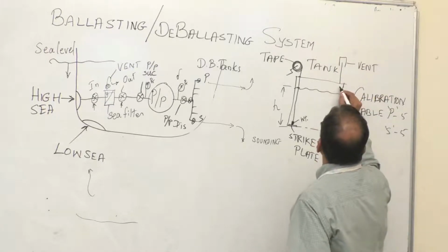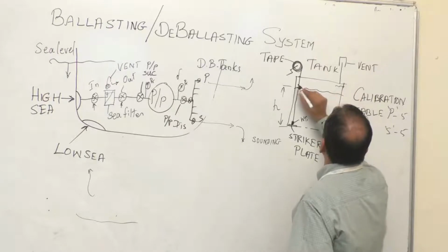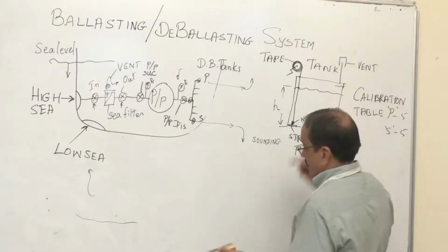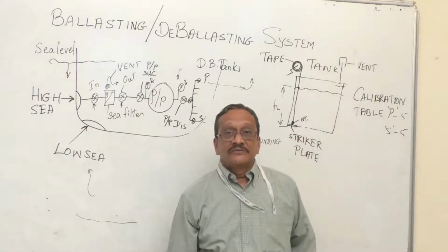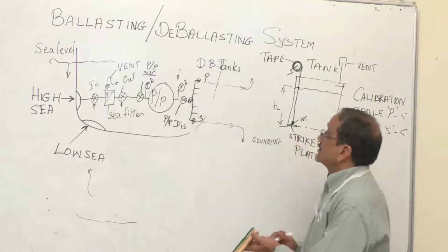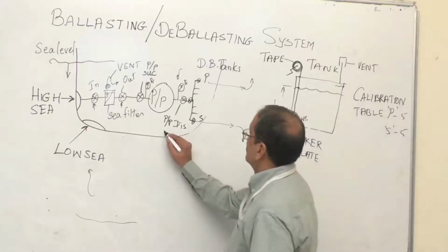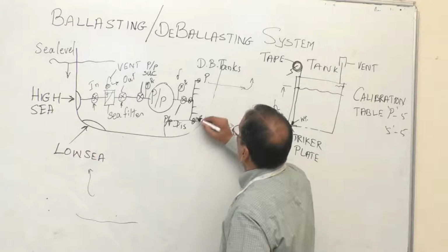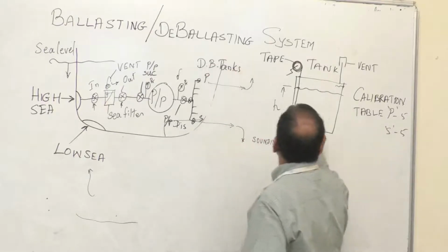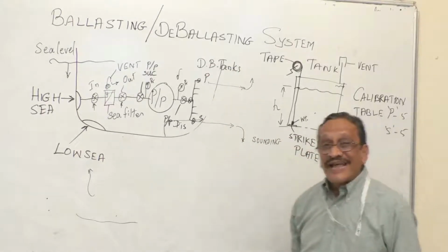So when you are filling up, ensure that your water is only up to this point over here and you do not see the water overflowing from the wing tank. That's mainly because this is at the bottommost portion of your ship. And your sounding pipe which is coming in over here, if your sounding pipe is getting filled up, there is too much pressure coming onto your tanks.